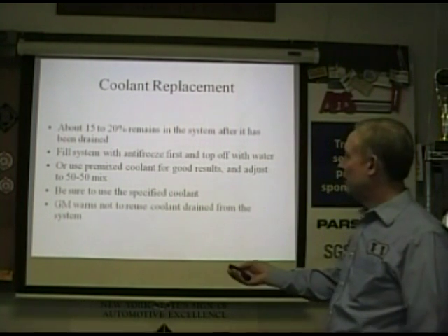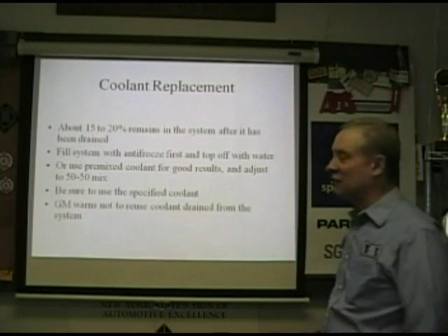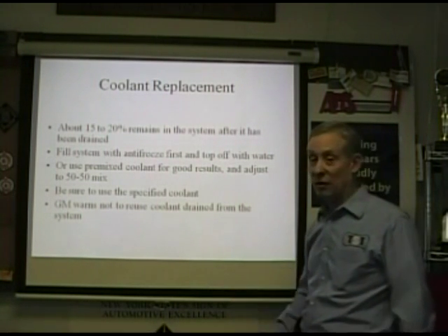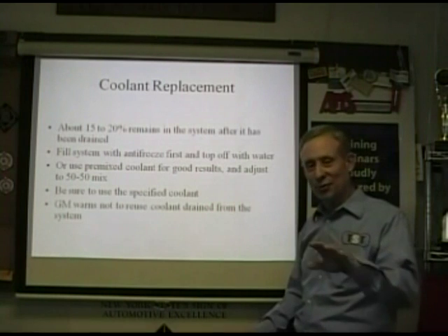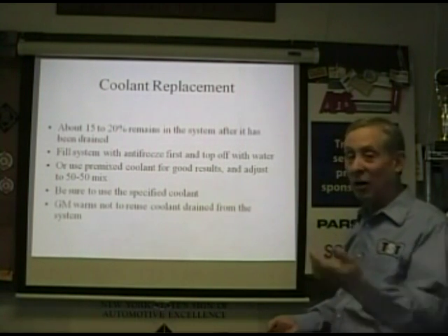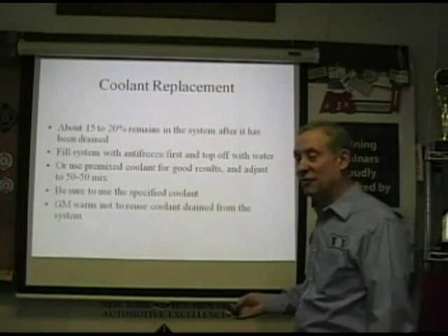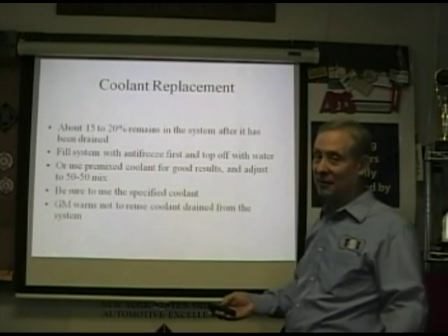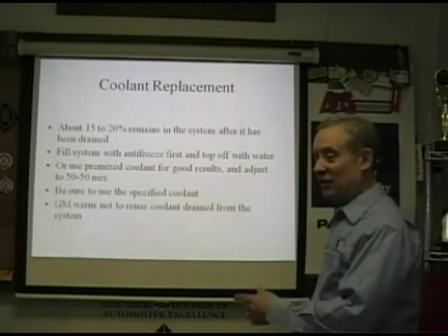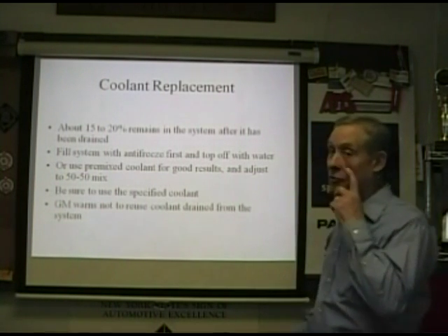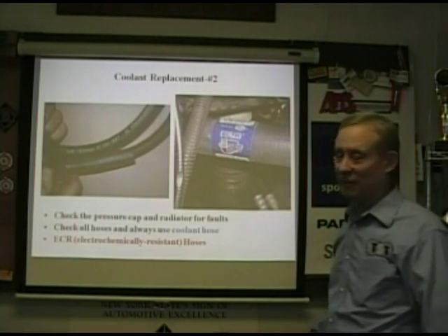All right. GM says don't reuse the coolant drained from the system. I think that's a general rule. Pierre recommends don't reuse coolant. If you take it out, throw it out. It's like the old rule about spark plugs: if you drop it twice, the second time it goes in the garbage can. In this case, don't use coolant again. Drop it in the recycling.